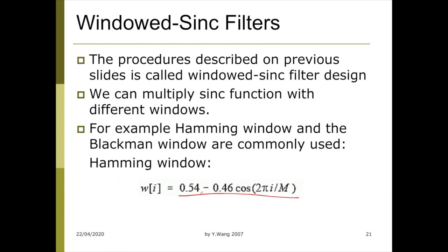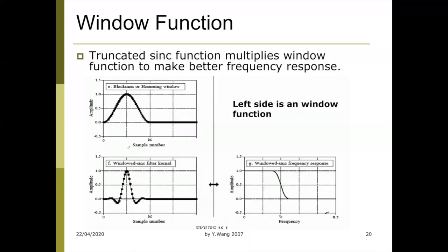It is defined in the digital domain. Those are the specific coefficients that result in a Blackman window shape. Essentially, what the window function does is smooth the sinc function and produce an improved low pass filter curve. You can see this curve has been improved, the pass band ripple has been removed, but the sacrifice is you probably have a longer transition band.